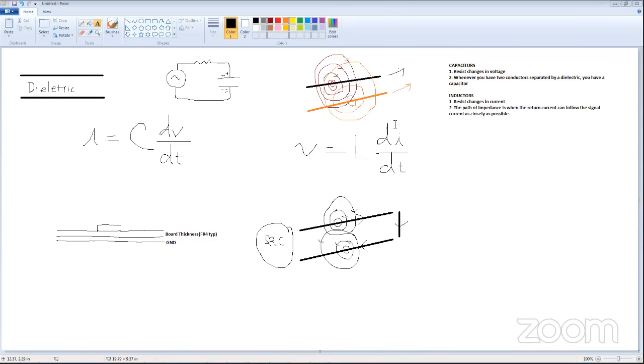And John brought up another good tip, one that our old autorouter does automatically. Reduce coupling by keeping adjacent traces at 90 degrees. Because if you do that, then the field lines can't interact. They're not in parallel, so you basically avoid inductive coupling altogether.